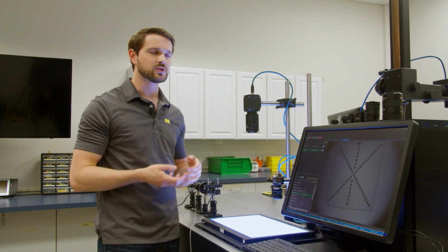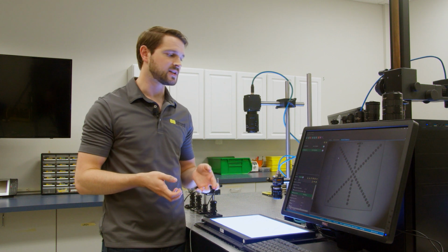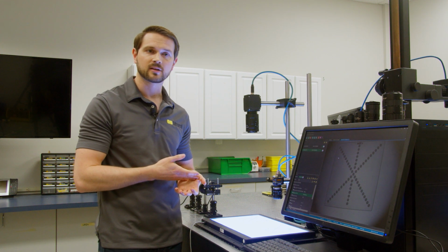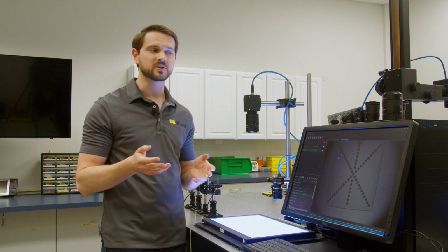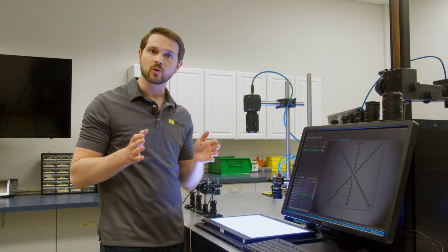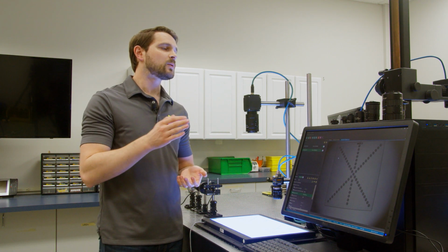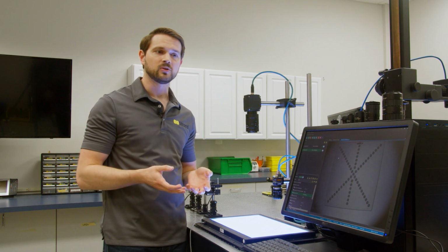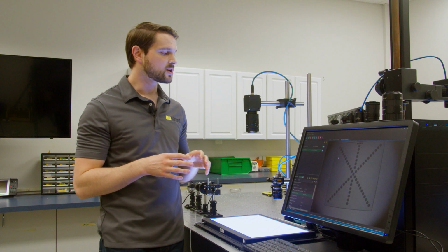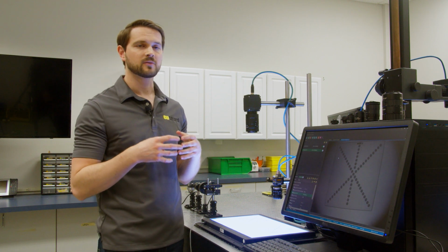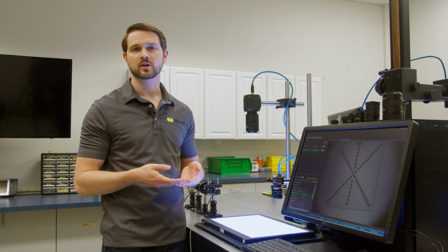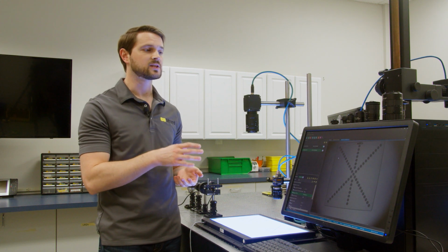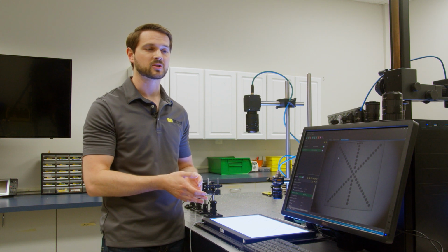So in this particular case, you could use your relative illumination curve and say, well, hey, I know that I'm actually not going to be using much beyond the 2/3 inch diagonal position, but I do need that extra horizontal and vertical. Now, what the relative illumination curve isn't going to tell you is what the overall system illumination is going to be like. There are some things that go on within the sensor itself from micro lenses and also software correction and gain correction that can actually change what this looks like from an overall system level perspective.